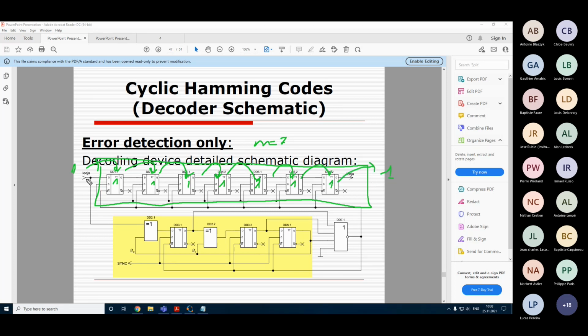So it takes 7 time intervals to get from input to this position, and at the 8th it will go out. At that time we already know if we have an error or not. So this is basically a delay line to wait for calculation of the syndrome.